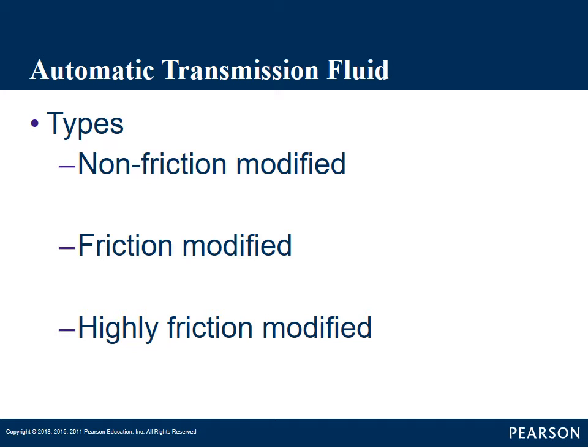In non-friction modified transmission fluid, it doesn't have any additives to help those clutches slide or slip together. When they grab, they engage really hard. That's why hot rodders used to put it in their racing transmissions. So the idea is if you're slipping them a little bit, you're burning them a little bit. However, in most applications, you're not going to cause much issue with a little bit of slipping.